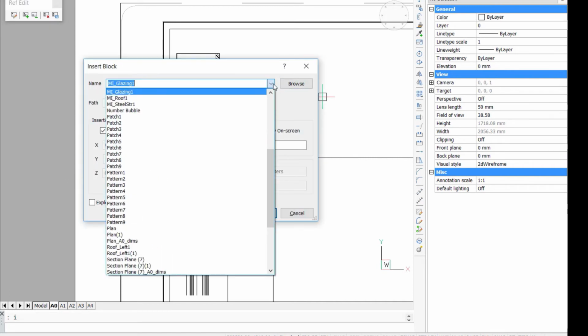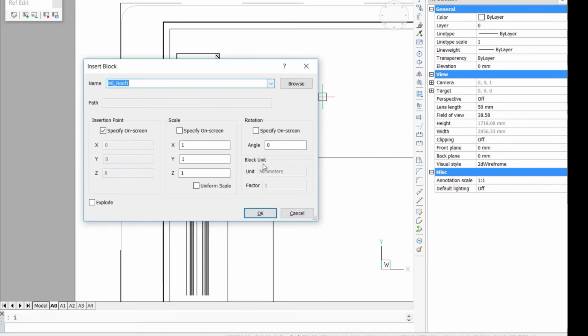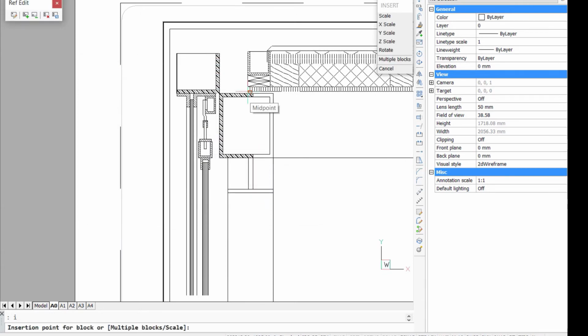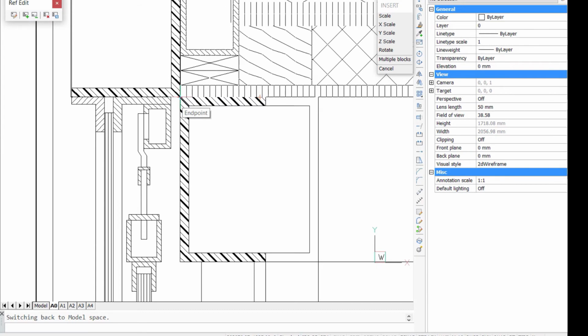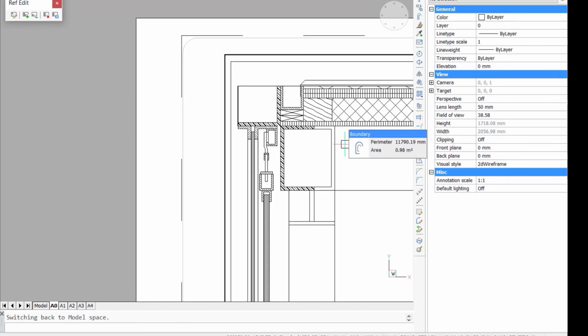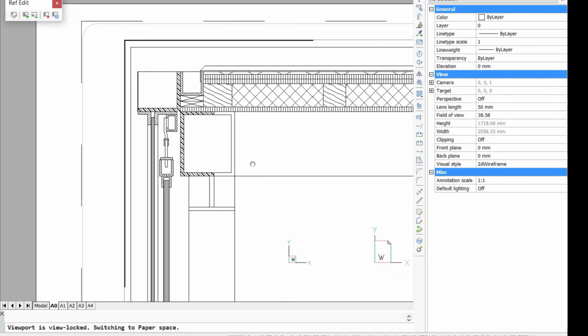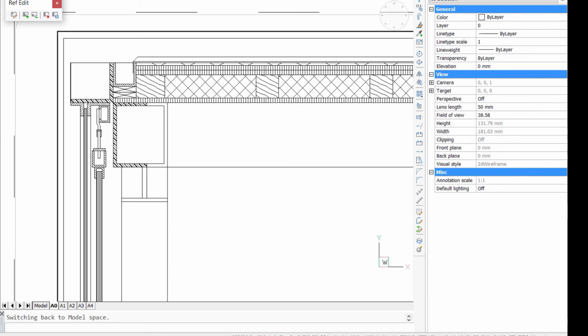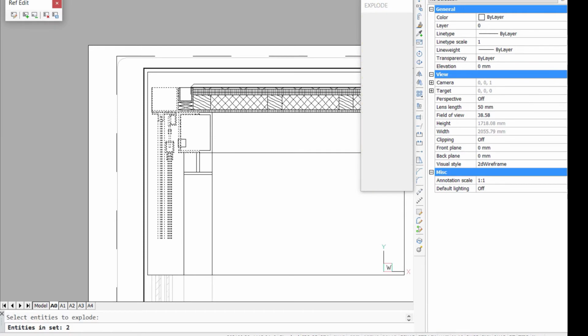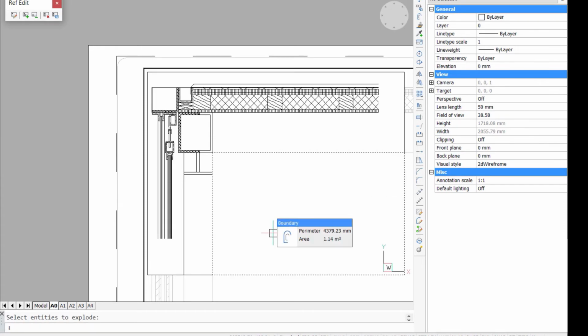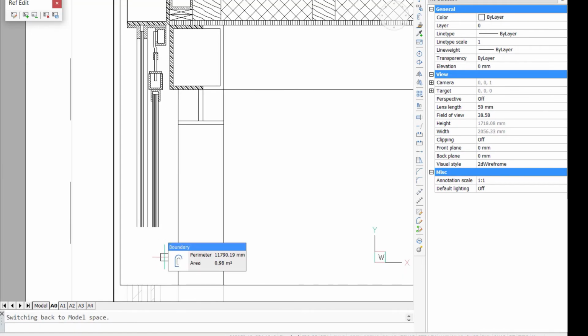The third block focuses on the roof, and the inclusion of an internal gutter at the edge and the roof composition, which includes sheets of plywood, insulation, and wood supports between, and a copper panel on the top. We'll make some final edits to get the visual representation correct for the detail geometry.